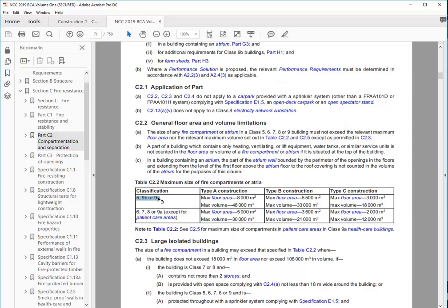So if you're confused by that, hopefully, again, you can just put something for the ground floor. And for the class 2 part, again, it doesn't have a requirement for the size of fire compartments. Deliberately. Right? Because you're not going to have a 2,000 square metre unit. I don't think there would be one that size, or 8,000 square metres. You think there are any units that size on the planet? 8,000? Of course not. No way.